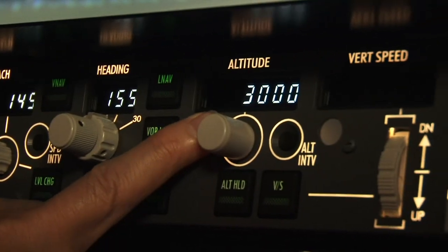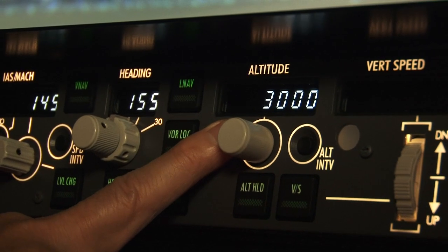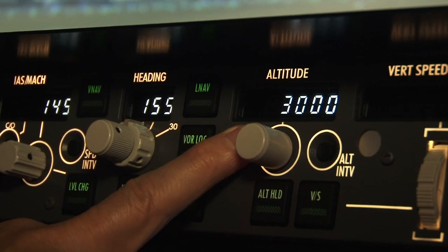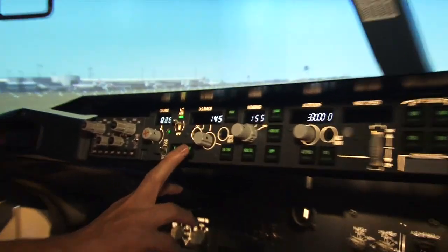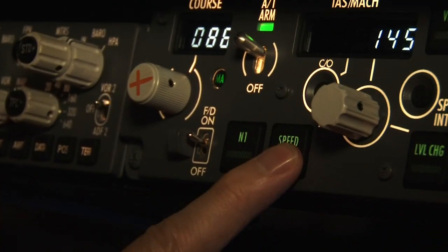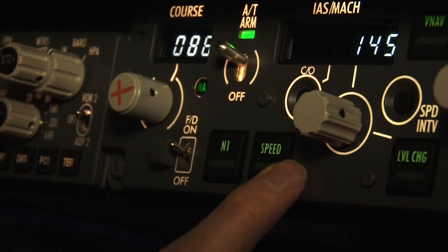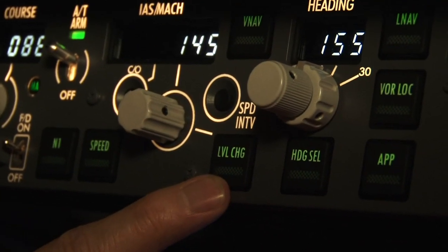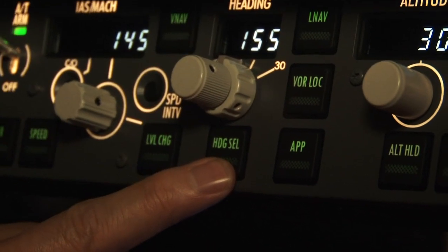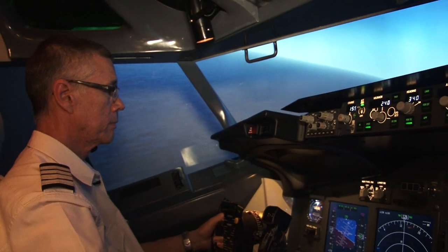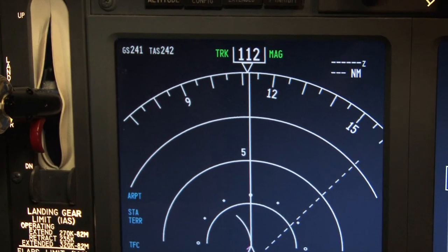And next we have the altitude selector here, so to control the altitude of the aircraft. We have different mode selectors as well to control the speed of the aircraft by use of the autothrottle. We can also climb or descend the aircraft by using level change. And when we're using our flight director system, we can engage a heading select, and that will then command the